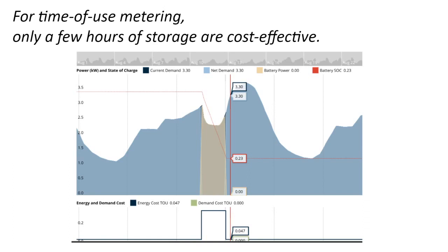With time of use metering, not like a commercial kilowatt demand charge, but time of use metering, if you have some kilowatt hours where you're paying that peak rate, it's bad, but it's not as bad as running out of battery capacity for demand savings.